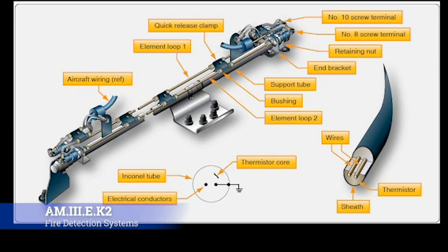In some aircraft, it supplies the nacelle temperature data, so it'll feed into AIMS, which is the aircraft in-flight monitoring system, and it lets you know, "Hey, look, in the nacelle, this is the temperature out there," which has its advantages. It becomes like another data point for decision making. It integrates temperatures along the entire length of the system, and provides average readings rather than just local hotspots.